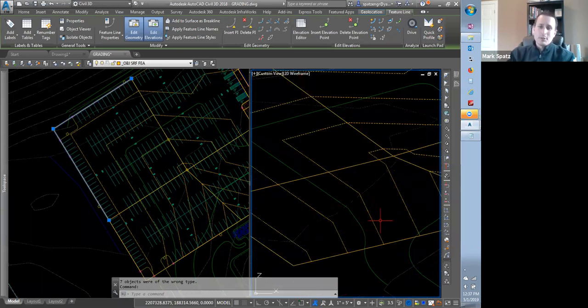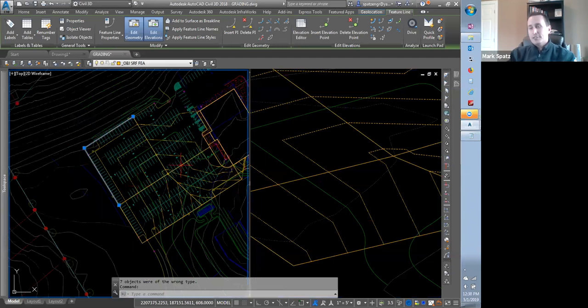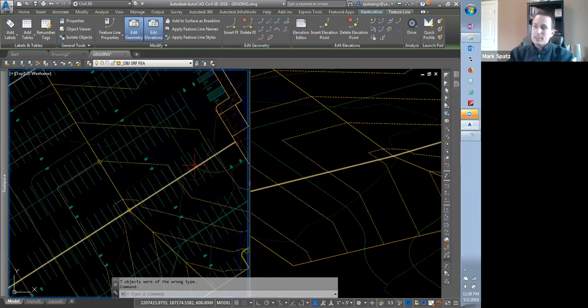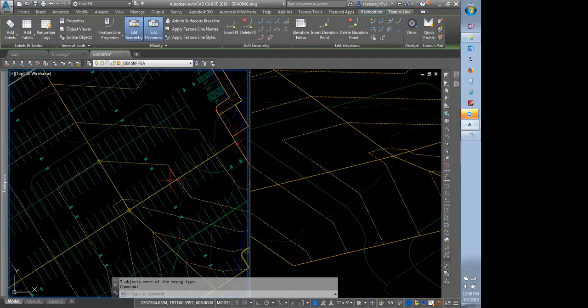The intent is that when you're grading, you're not mimicking. If Chris draws up the contours, you don't just trace the contours in and make a surface of that. But to grade in Civil 3D, this is how you do it. When Chris is doing this by hand, he's doing this with the ruler. And then he's ticking off little spots of where this contour would cross when he has his ruler sitting across here. He's putting a little tick. And then he's doing the same thing over here, and down to here. And then when he's done, he just traces where those contour elevations would be.